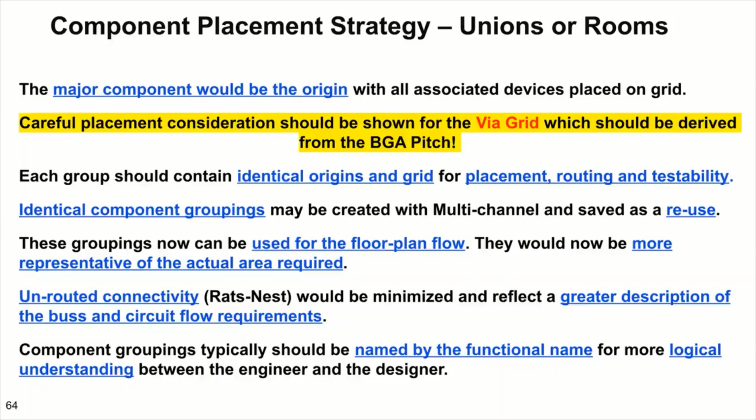is readily available for every pin. And with identical origins in grids, the placement and the routing and the testability is going to be improved. And we can save off these as reuses if we want to with different software, depending on how your software names that. But again, it's a repeatability from circuit board to circuit board using a saved off reuse.